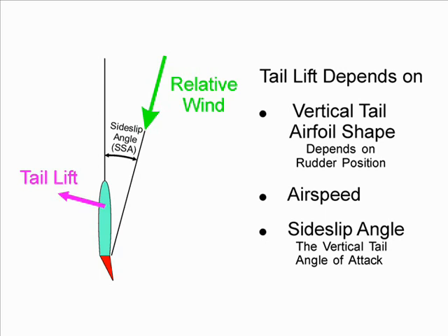In the following video, we will see that as airspeed is reduced, a slight yaw away from the operating engine increases the sideslip angle and tail angle of attack so that the necessary tail lift can be maintained. However, the change in sideslip angle changes fuselage lift, causing centripetal force and the resulting rate of turn. Banking into the operating engine can provide horizontal wing lift to reduce the centripetal force to zero. We can now see this bank angle effect in action.